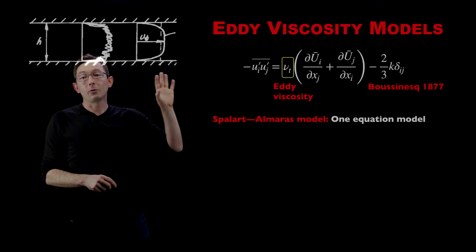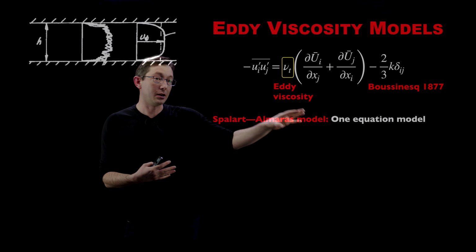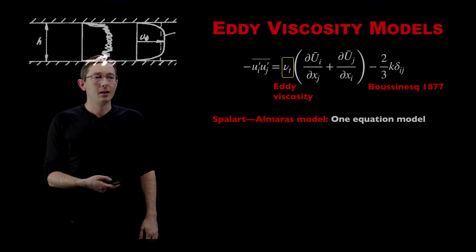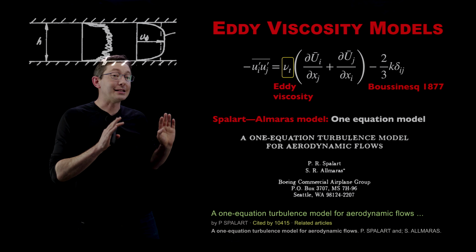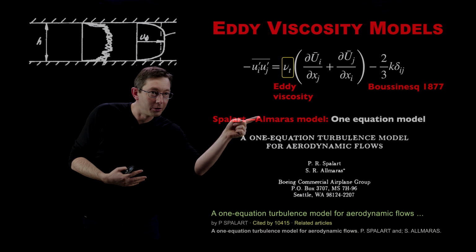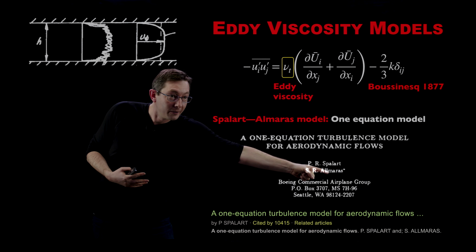Okay, so another really, really useful model in the literature is the Spalart-Allmaras model, which is a 1 equation model, so more efficient than K epsilon. And it's actually been tailored for aerospace applications. I'm sorry, autocorrect killed one of the L's here. This is 2 L's, Allmaras, here.